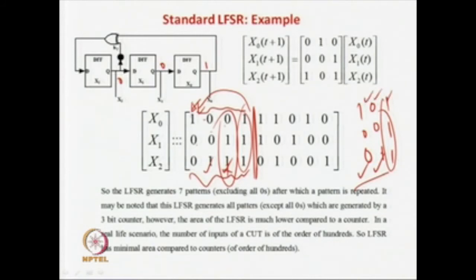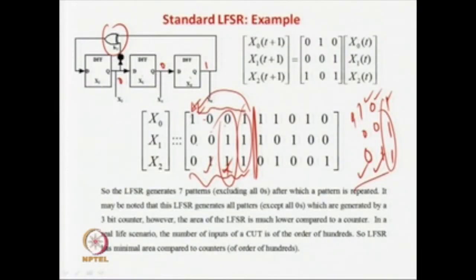You will find that it will take many more gates than a single XOR gate. You have to do it using Karnaugh map optimization or Quine-McCluskey optimization. This is the current state, then if you apply a 1, you go here and the next state will be here, and so forth. Then you go for minimization: this is 1D, this is 1D, this is 2D, this is 3D. So, 3 D flip flops are there, and you have to optimize the inputs for all of this.